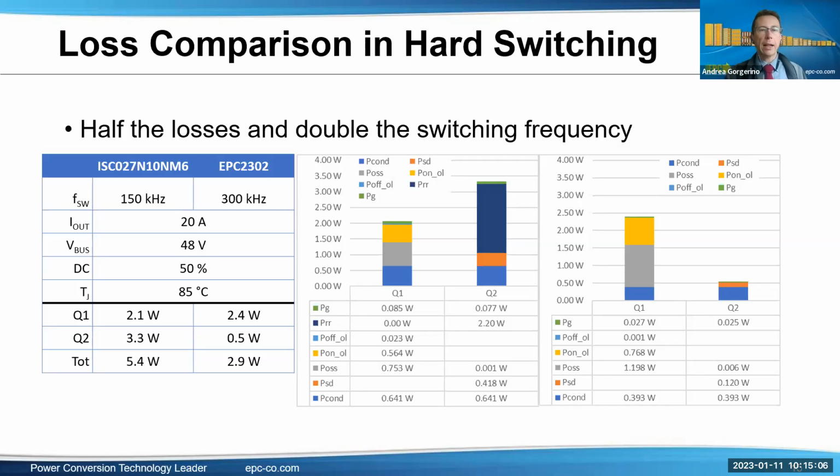And the reason for that is that GaN FETs switch faster, again, with the same gate driver and same assumptions, so you can use lower dead time. The assumption for dead time here was done in a similar way for both devices. Basically, it's 2 times the sum of all the transition times to give some margin. And again, since the GaN FETs are switching faster, the dead time tends to be much smaller. And this means you spend less time in that condition, which means lower losses overall.